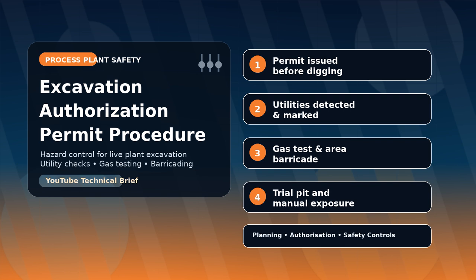So you will come to know the depth and the particular location, and then you have to mark it there. You can also transfer the same to your survey team so that you get the coordinates as well. This equipment is suitable only for detecting metallic pipes or live electric cables. If the cable is dead, it will not detect that. Everything you need to mark in that location.